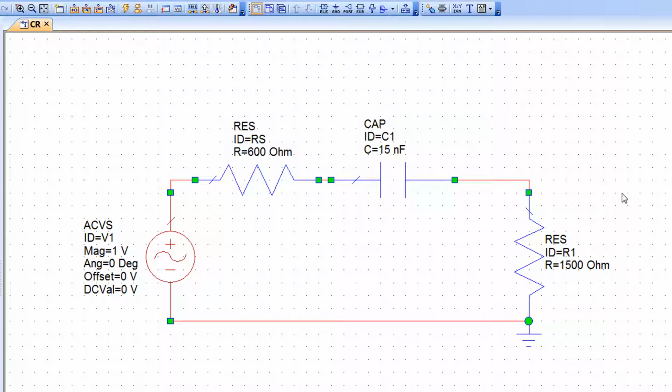I will need to measure both the input voltage on this side of the capacitor and the output voltage right here. Because remember that the PicoScope has got a non-ideal voltage source. So the voltage that this source here, V1, produces won't be the same once some voltage has been dropped across this internal source resistance here.